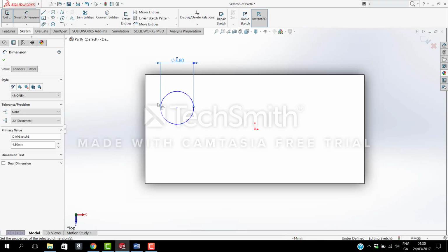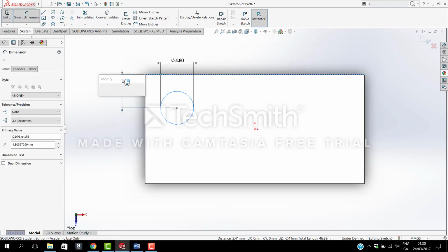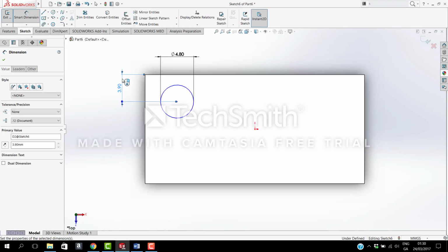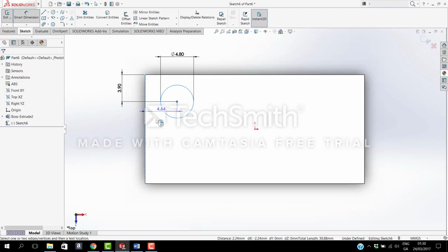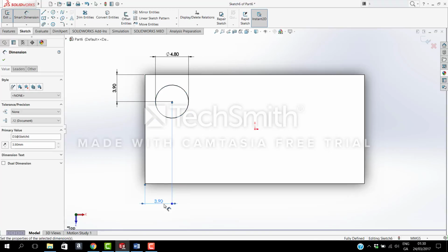As you can see, my geometry is still blue, so it is underdefined, so I must relate this to existing geometry. So I click on my circle, click on my edge, and dimension that to 3.9. And click enter. And I must dimension it again to the other edge, 3.9. Now my sketch has turned black, so it's fully defined, so I can proceed.